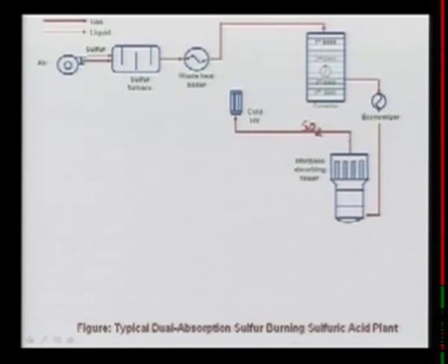The temperature here is a little low, so we bring it here and heat the stream a little. We are taking a little heat from here and heating up this SO2, using this tower, and then you can see that we take a small stream out from there, heat it, and pass it for the conversion.